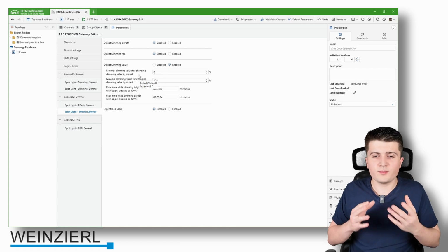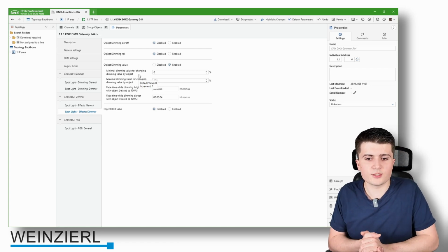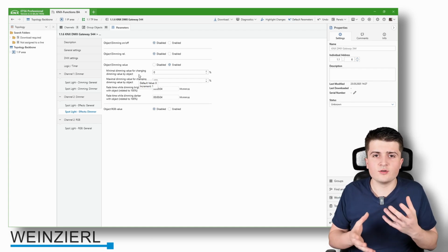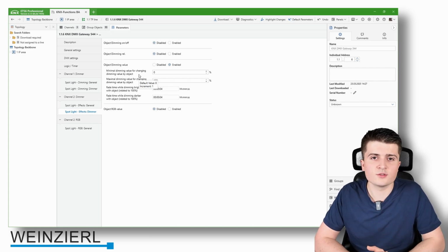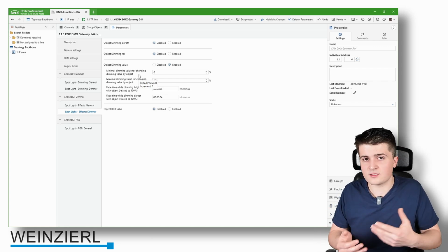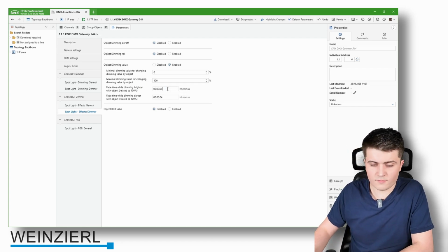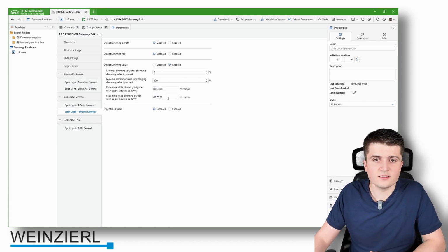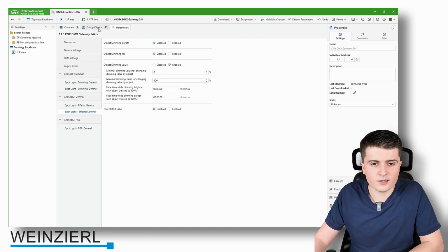And now here you have to bear in mind that this gateway expects a value from 0 to 100%. 100% means the value 255. So here you have to do some manual calculations to know which value you have to send for which effect. That's also based on the device that you are using. But what I would also do is disable this fade time, so that when I want to activate an effect, it's directly activated and it's not dimming to this value.